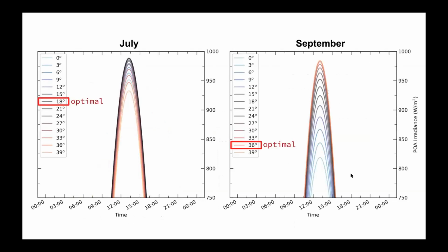Okay, so the next thing we looked at is, right, that previous plot was just looking at global horizontal illumination, which is just if you have a flat plane on Earth. But most solar panels are tilted for a reason, and that's because that tilt affects the performance, and depending on the sun's location, that also has an effect. So I decided to look at what the differences in terms of efficiency and radiance would be, depending on what our tilt would be.